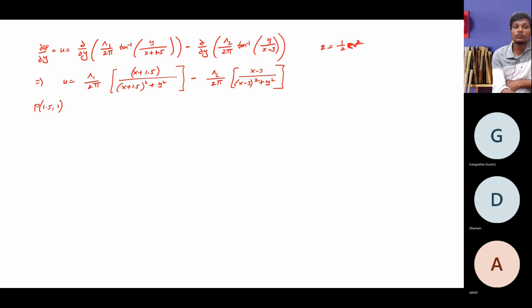So let me use these velocity components to substitute in the u and v velocity. If you substitute the coordinates, that is x equals 1.5 and y equals 1, then you will get the u velocity equals to, also note that λ1, that is for the source flow, has a value of 0.72 meter square per second per unit length. It is not correct to write meter square per second per unit length. It is not the exact thing. It is meter cube per second per unit length.